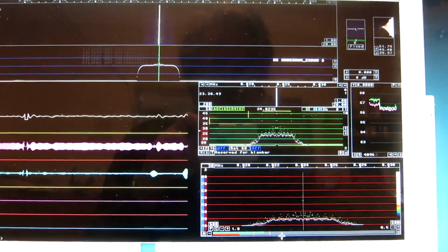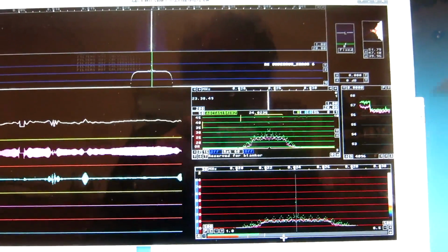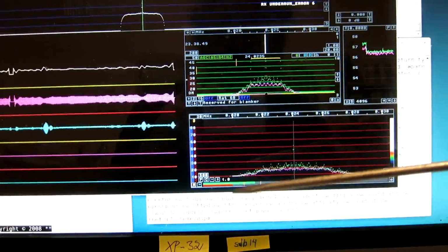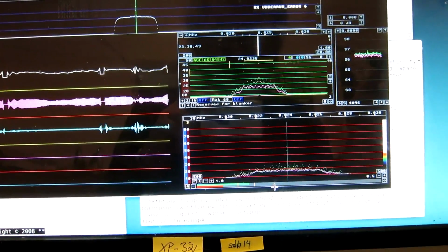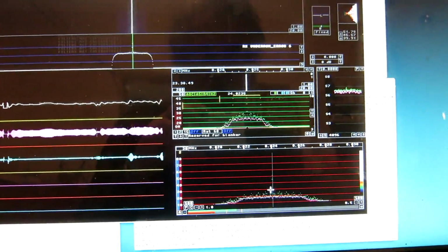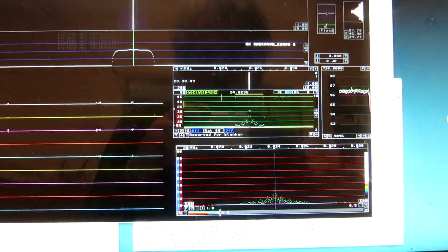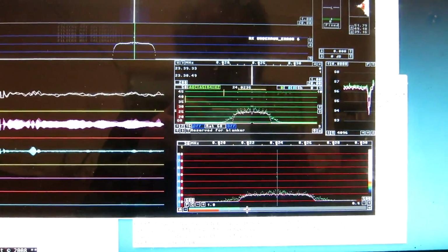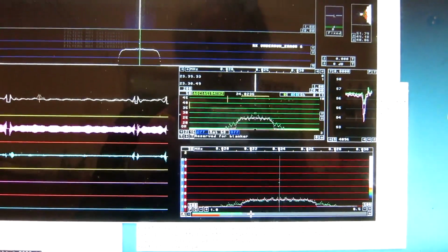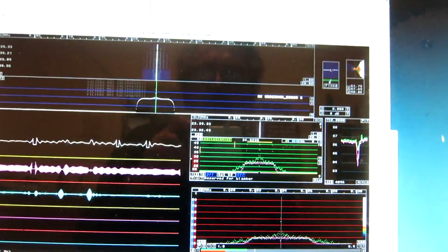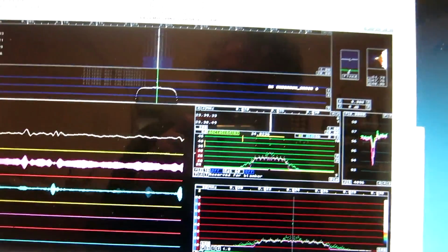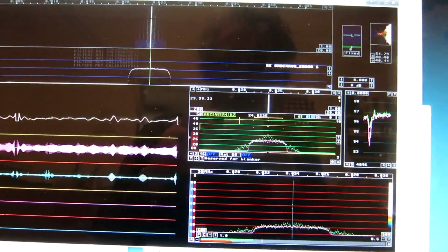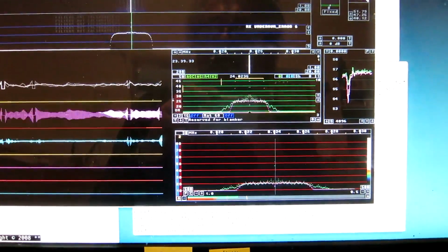And we can see here, the red bar is the signal plus noise in the orthogonal channel, the out-of-phase, while the green is the AM station plus the pulses. I would like to place the threshold something like here, if I could do it for the red bar only. I haven't implemented something like that in Linrad, but it is doable, and one could do somewhat better processing than Linrad has had before, maybe equivalent to the vectorial blanker that is implemented in Perseus.